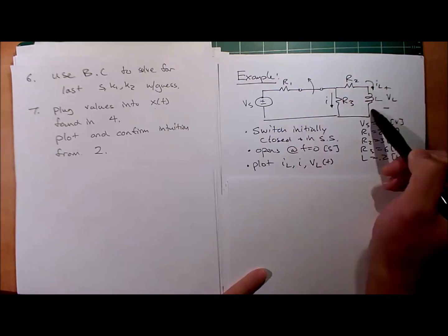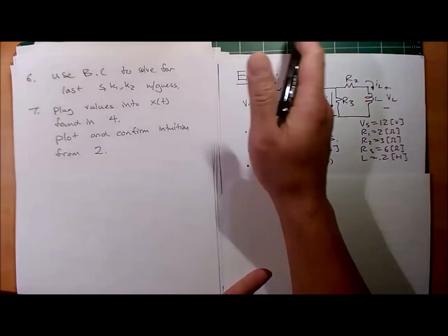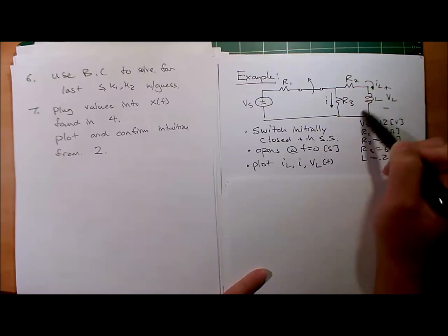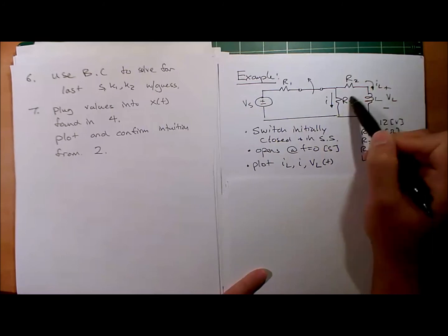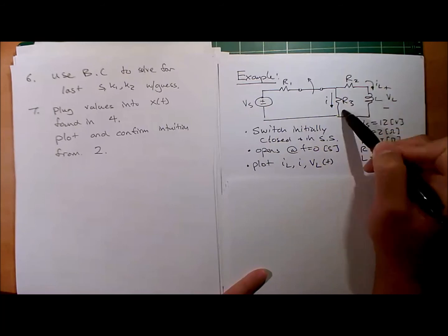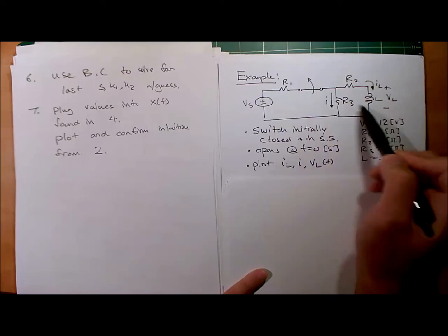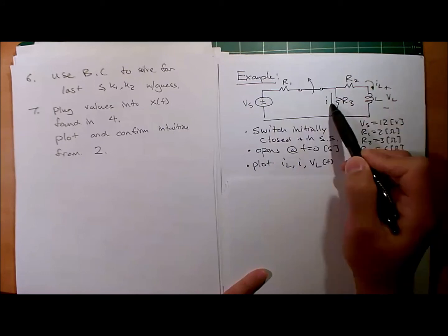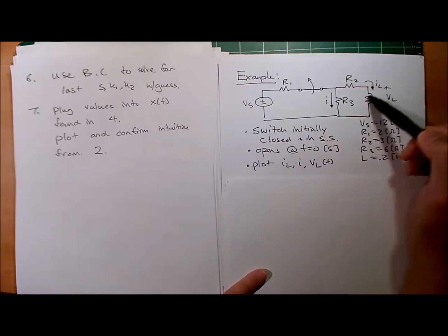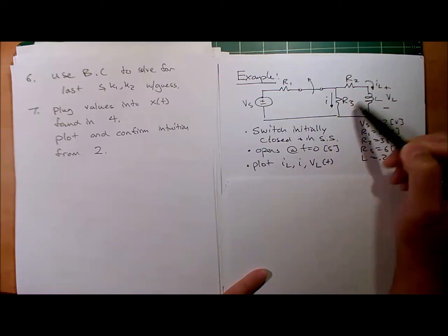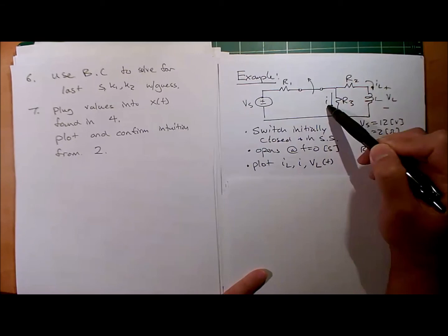Okay. When I open it, what happens? This left part of the circuit is gone, and now this inductor will have current through it. It's going to want to not change its state. So it's going to try to keep current flowing in this direction, right? And what's going to happen? Eventually, it'll burn out on these two resistors, okay? So let's try to imagine what's going to happen. Steady state, current's flowing down in both branches. Switch opens, the current in this branch immediately flips to the other side because now these two are in series, and this inductor is going to overpower and keep current swirling in this direction. So IL will stay positive and I will flip negative, okay?